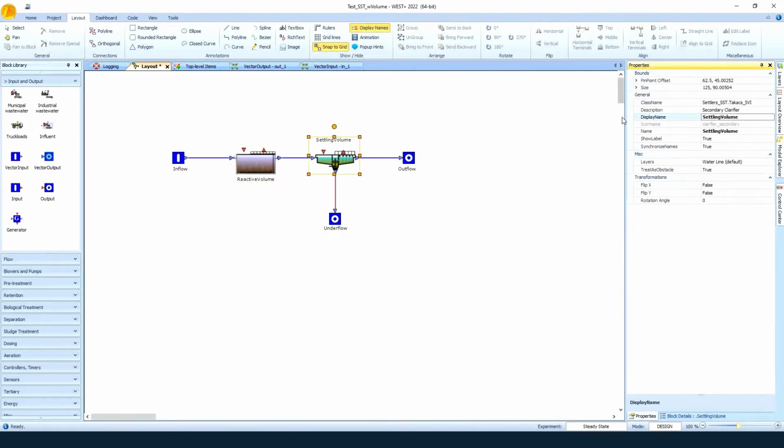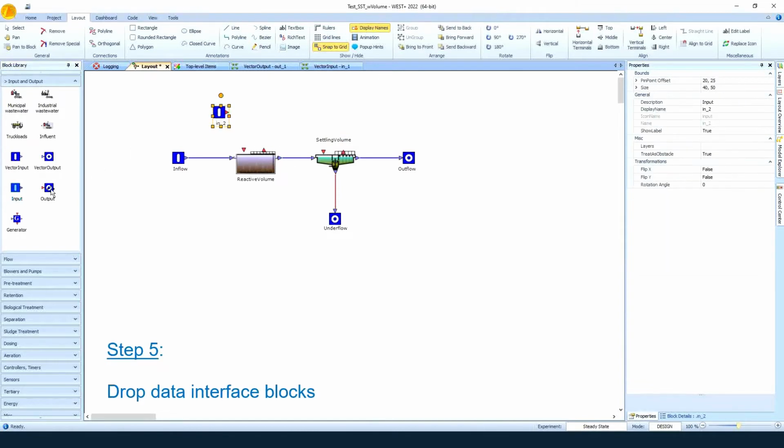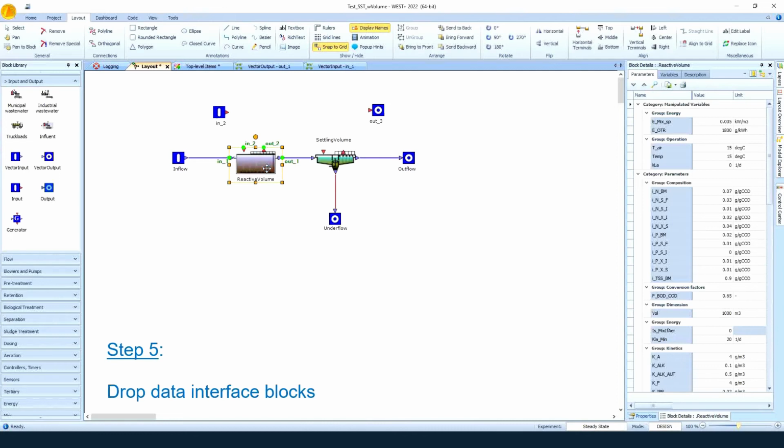The coupled model has to be integrated into a larger process model through the usual Flux interfaces. We also have to measure certain quantities through sensors and control other quantities through manipulated variables with data type terminals, which require data type input and output blocks.